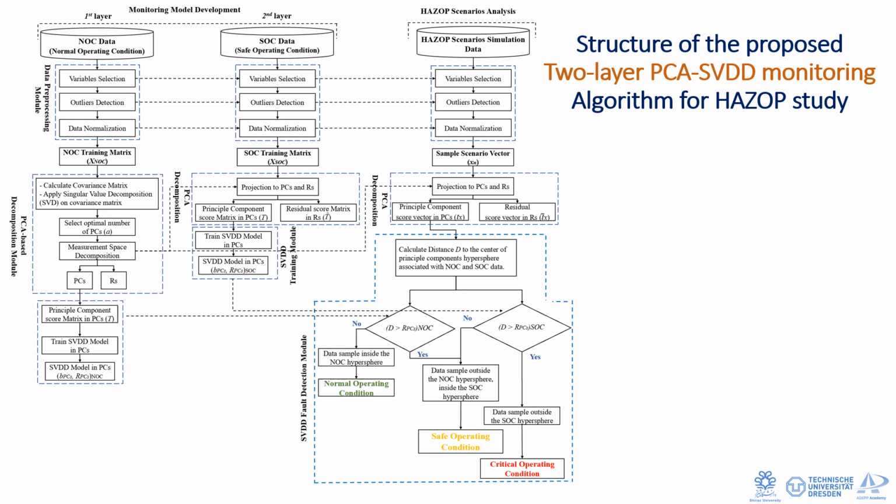Multivariable process monitoring is an effective method for monitoring of process key variables for abnormality detection and diagnosis. This monitoring technique can also help alarm management in the process industries. The novelty of this research is as follows. First, MPM is applied to improve the understanding of the complex HAZOP scenarios by a holistic interpretation of the process dynamic behavior. Second, besides the common normal operating region layer shown in many process monitoring analyses, and since the focus of HAZOP study is more on critical process conditions, a new multivariable process monitoring layer is invoked to identify the critical conditions of process variations further than the normal operations.